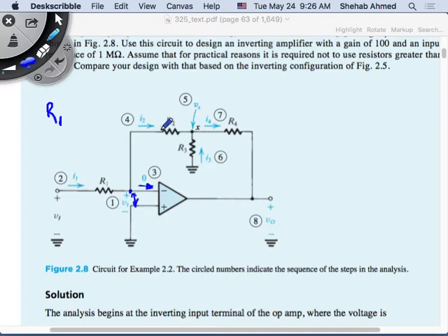So I will do nodal analysis to find the voltage Vx. I will find Vx, and what we will find is an equation for I4 that will show that this I4 can be amplified by placing this resistor in parallel. In the previous circuit, we didn't have this resistor connected to ground, right? Because we didn't have this resistor to ground, the output voltage depended on what?